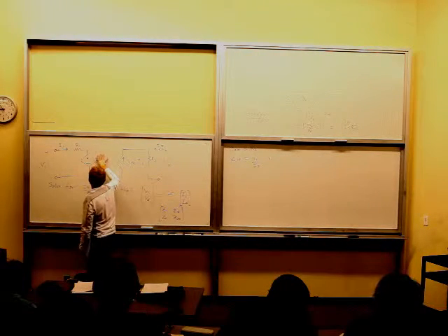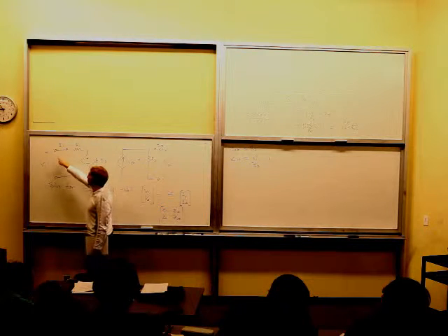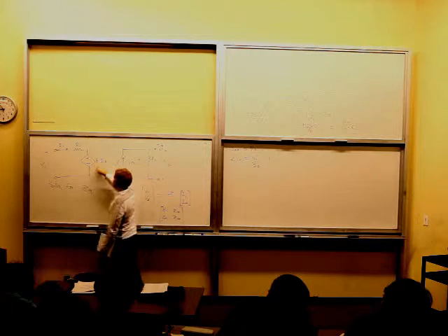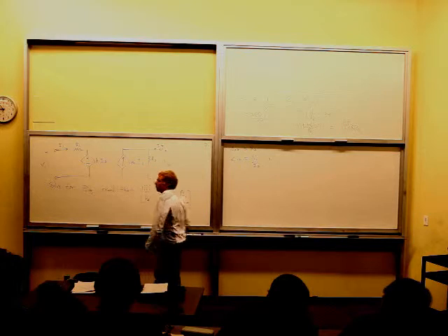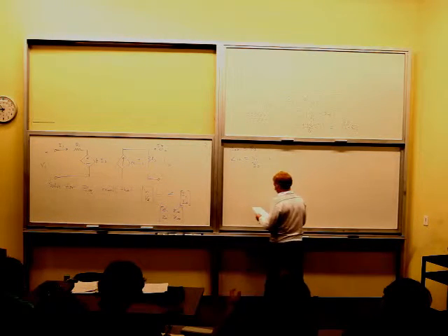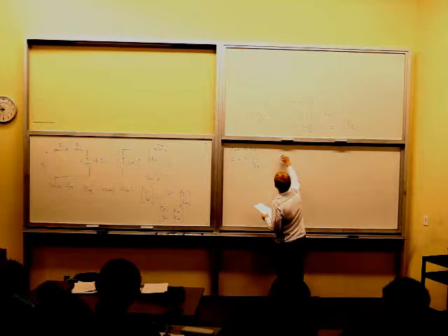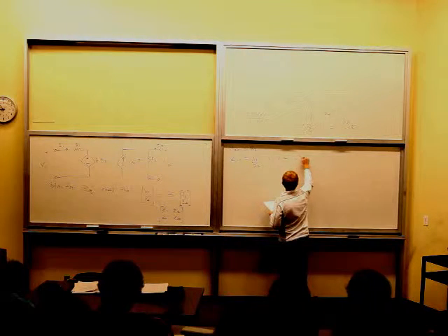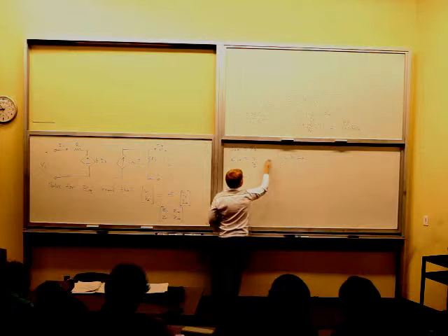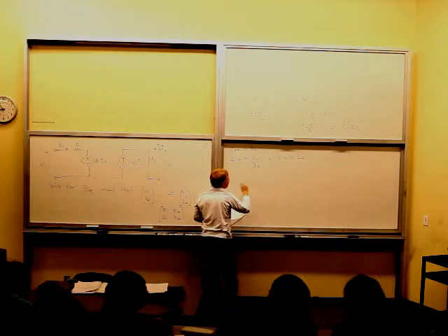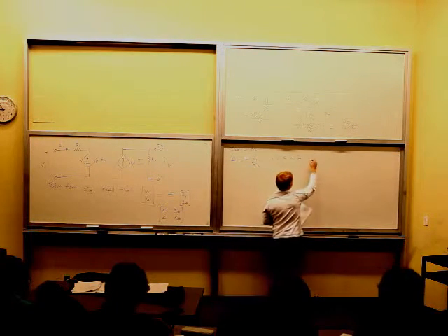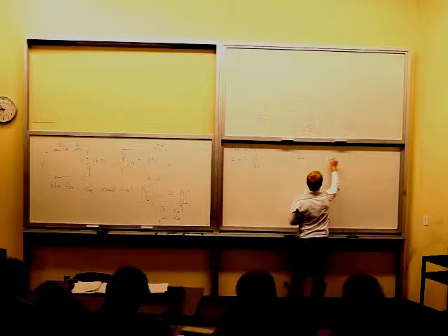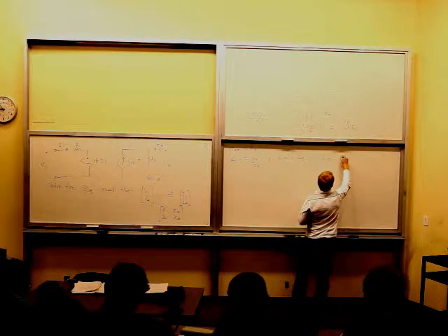Whatever this dependent source is going to be your voltage. So V1 equals B times I2. That's nice because I can sub that in and the I2 over I2 will cancel, so I end up with Z12 just equals B.